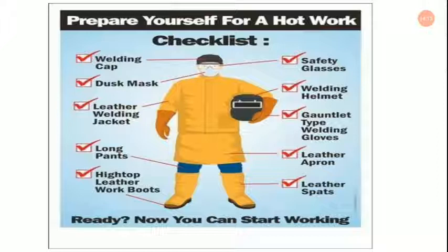If welding above the ground or from a ladder, be sure that there are no combustibles underneath. Don't forget about co-workers who wouldn't appreciate being hit with slag or sparks from the work. Fire watch personnel may be required.